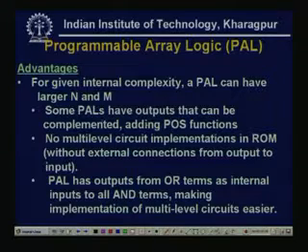We see that some PAL functions are output functions that are complemented. So, here we get again some more minterms using this. Now, there are no multi-level circuit implementations in ROM without external connections from output to input, but as here the PAL has a fixed OR, if we add some more additional circuits to the fixed OR plane, then we will have more choices.